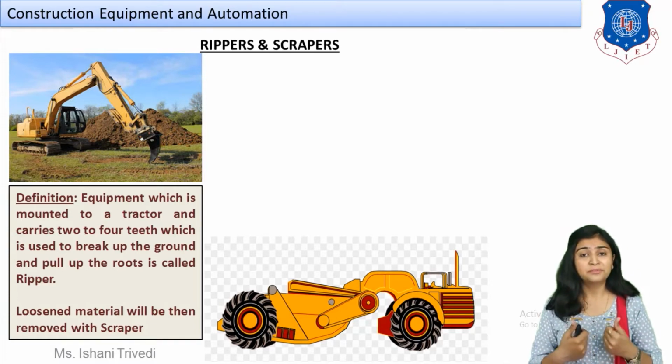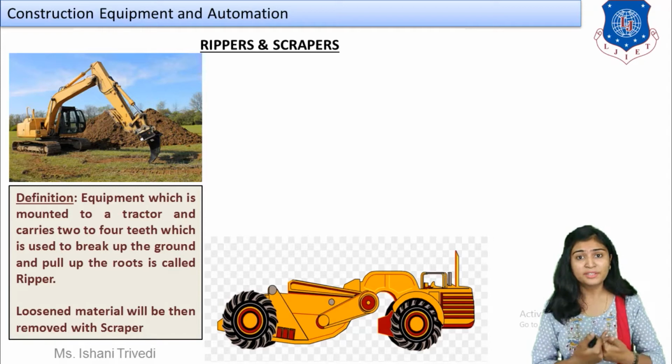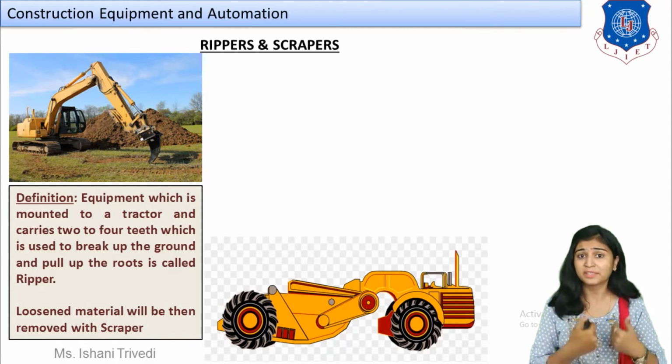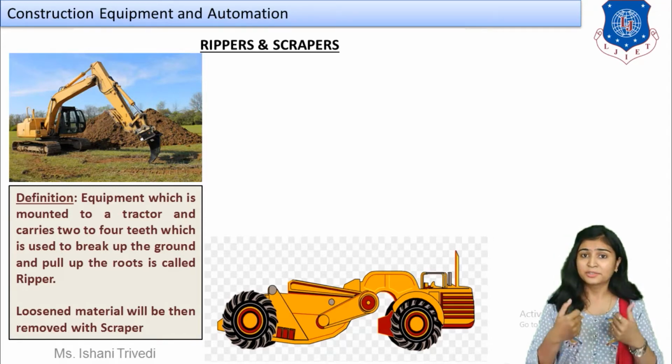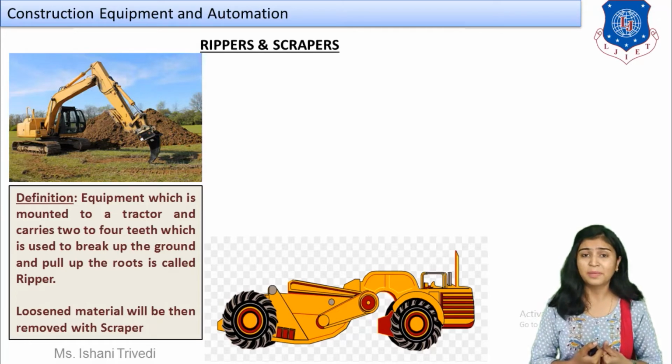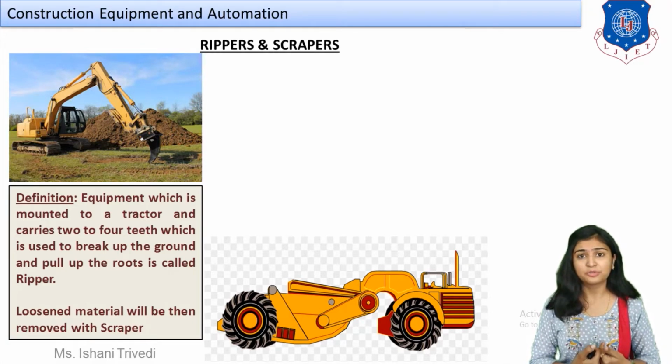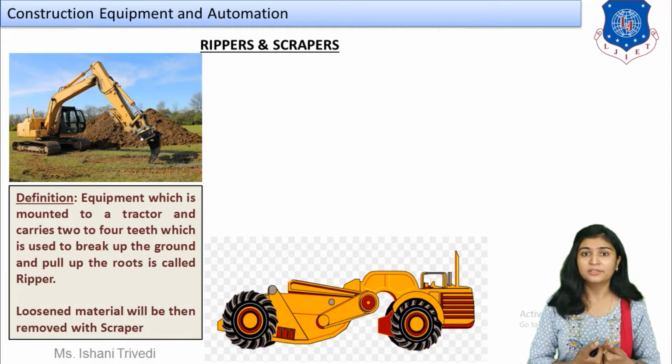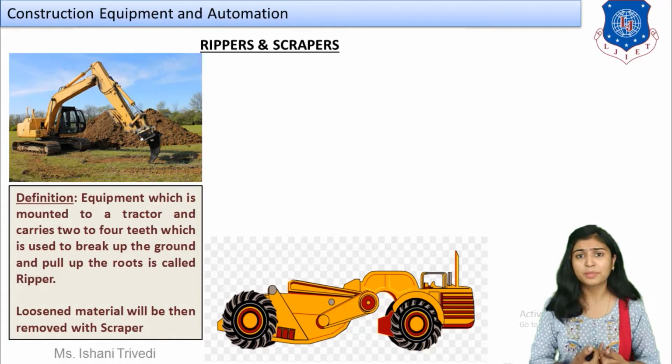And if you are dealing with soil where boulders, rocks, or gravel are present, then your simple excavator or simple power shovel is not going to break it. Instead you will have to use the equipment called rippers, right? Rippers are used for ripping the rocks present inside the soil. Ultimately you are excavating the soil, nothing else big over here.